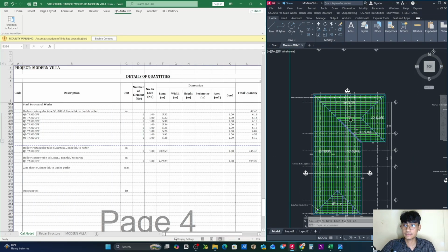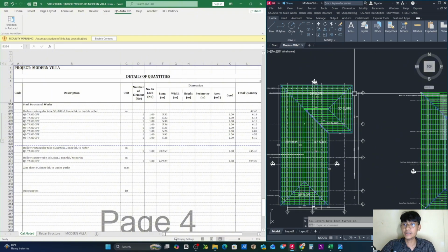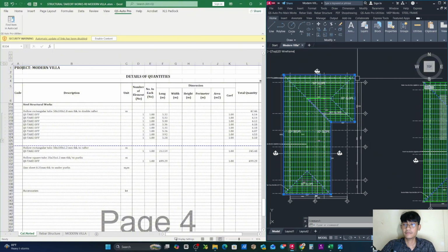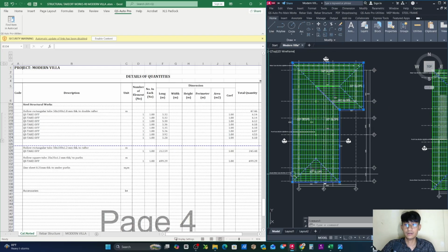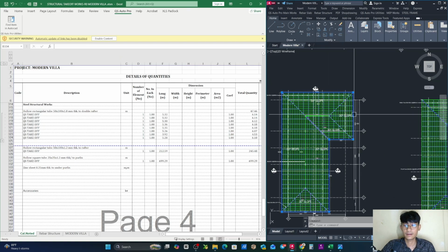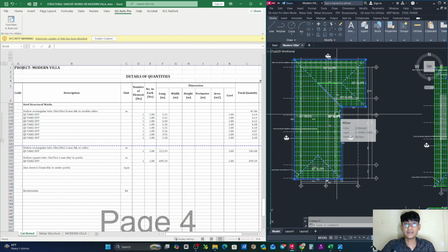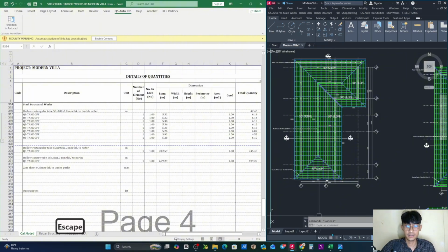Okay, now all we need to do is get the flat layout area, the horizontal one. As you can see, all you need to do is just polyline around it based on our design. Okay, and then we will take it and divide it by the cos of 30 degree as above, with the same formula.